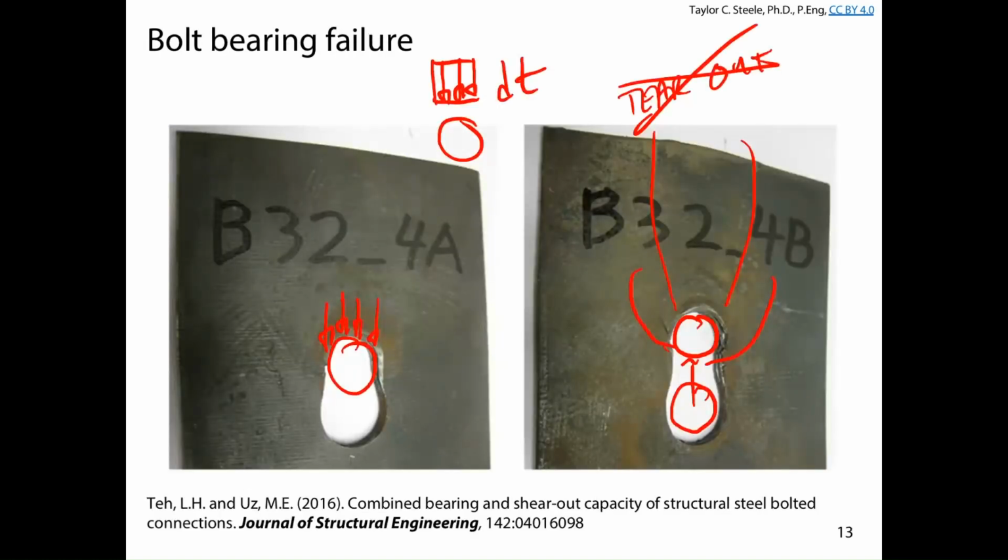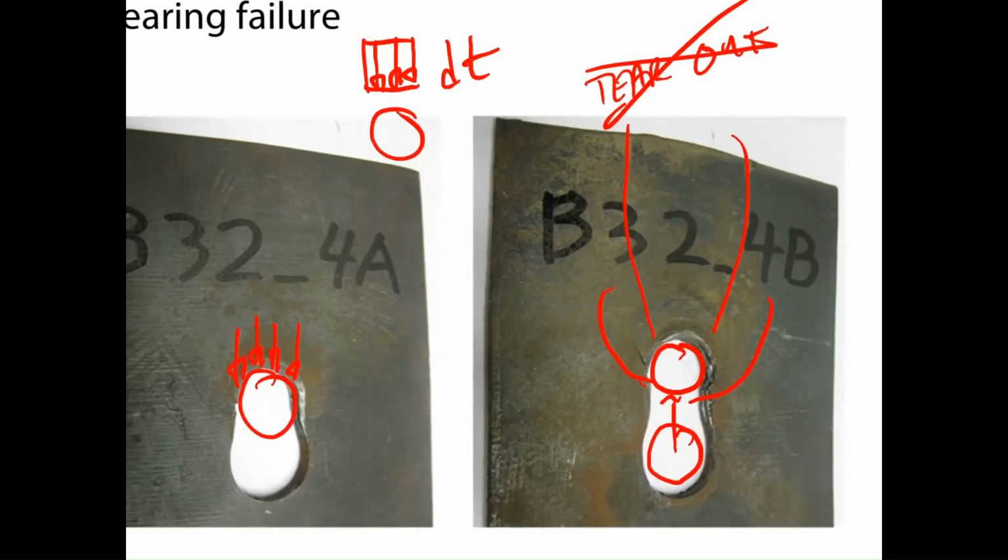And that's basically to account for the fact that the bearing failure happened through a significant amount of yielding in this area that's downstream, so to speak, from the bolt hole itself. And so to mobilize that bolt, all this area around it has to fail. The idea is if you spread out the stresses from the contact area to the area that's actually filling in bearing, it fans out, similar to what you might have in a foundation on soil. The stresses fan out this way.